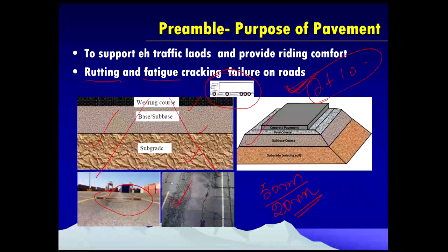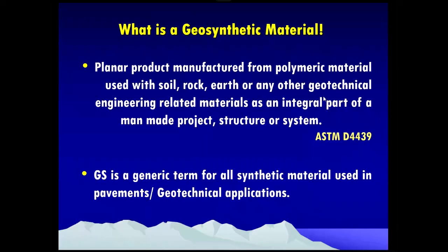Extending the life of the pavement is one benefit, and sometimes it helps in reducing the thickness of the base and subbase layers, thereby saving material and saving the cost of construction. That is the motto, that is the preamble in using geosynthetic materials.